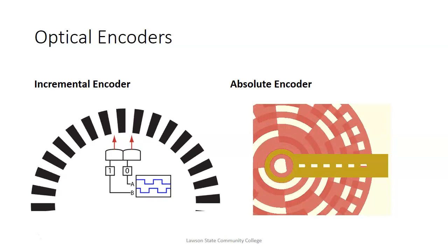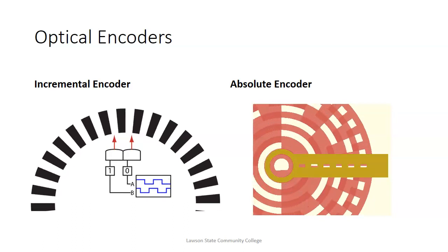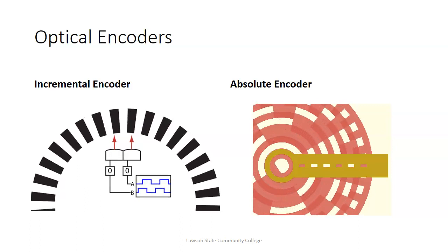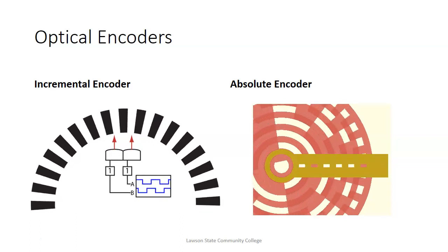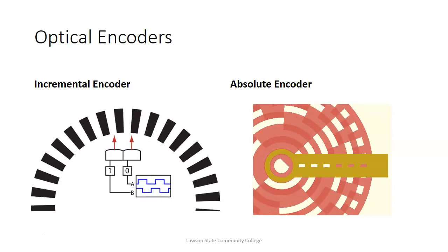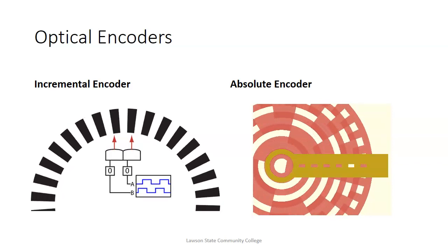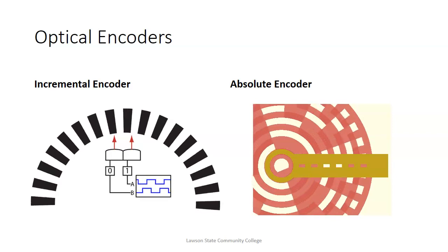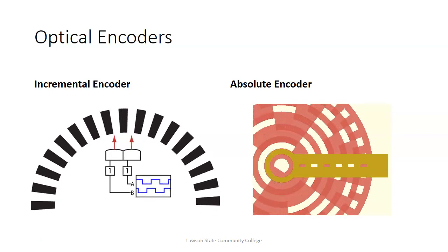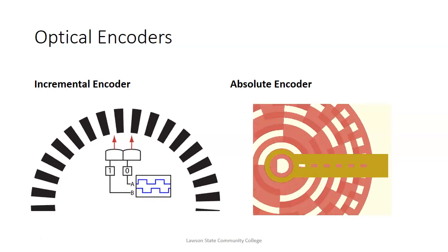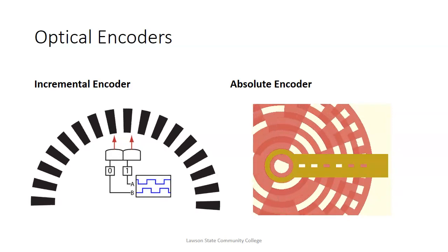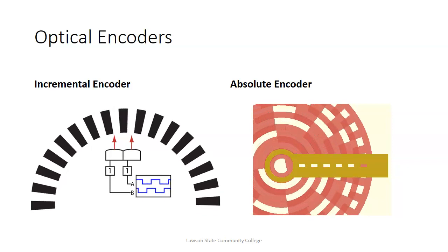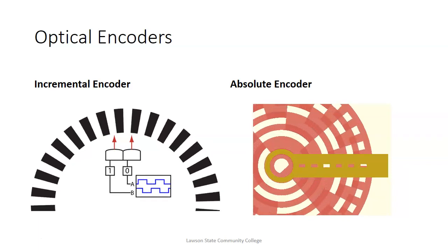The first one that we had was a Rhino robot, and it had limit switches on it. So if it ever lost its zero, it would just jog itself until it hit the limit switches, and then it would come back if we told it to origin itself. It was pretty good. That was the first robot we ever had, by the way, and that was one of those where they bought it, and they told me it was here, and I had to figure out how to program it. So that was interesting.